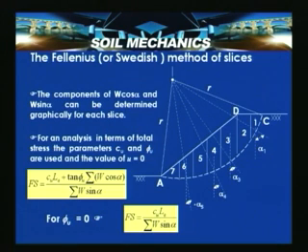So, here in the Fellenius or Swedish method of slices, a particular slope portion is shown and is assumed to be divided into 7 slices vertically. The entire portion A, B, C, D is divided into 7 portions vertically, and at the CG of each slice, its weight is assumed to act. So, from 2/3 distance from here, the CG of this slice weight is assumed to act.